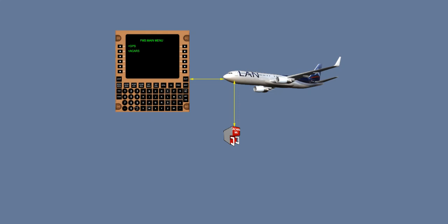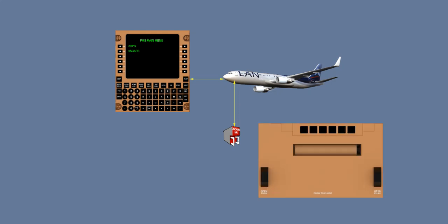Here you can see where the ACARS components are located on a typical installation. The management unit, or MU, is the heart of the system, located in the E&E compartment. The interface between the ACARS MU and the pilot is now incorporated into the CDU. The ACARS is also equipped with a printer to provide the crew a hard copy of received information. The Multipurpose Interactive Display Unit, MIDU, works as an interface to the ACARS system.